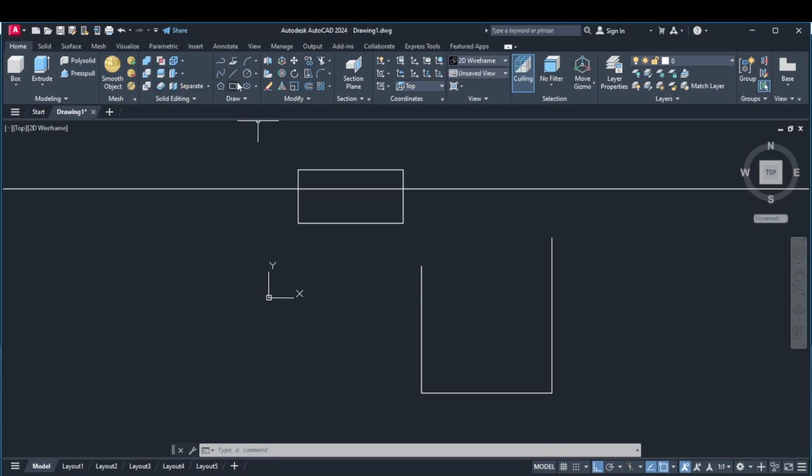So whenever you want to draw a circle, you'll see it has some specifications. For example, that one is midpoint. You also have that one as our end point. You have that one as our perpendicular. So all these are the object snaps of that object. So it improves drawing accuracy by aligning to the exact points that you want. So that is OSNAP, or the object snap.